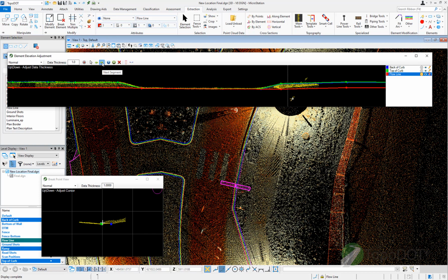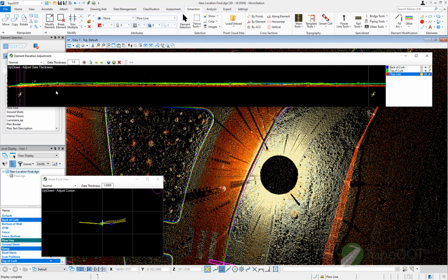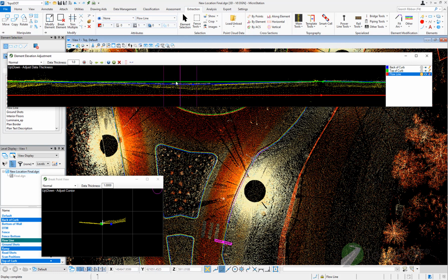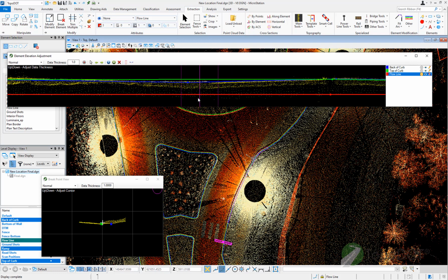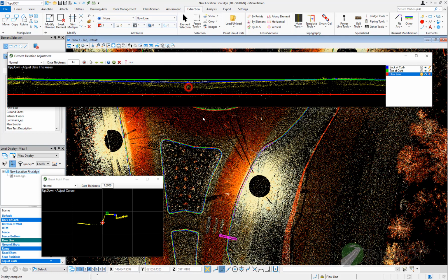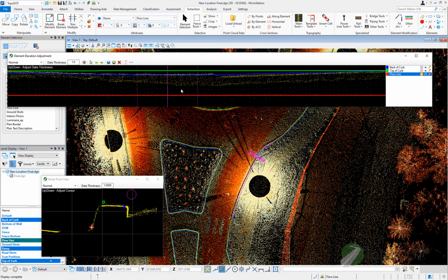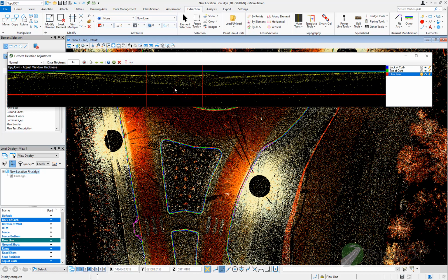So you can quickly address those areas that clearly have issues or that need to be adjusted. And so for example, here we have another area where, because I have the hollow points, that means that those nodes have not been introduced, and I have a flow line there, a back of curve there that is being created properly, but not the other points. So first I'm gonna delete any points I have there, and then I'm going to insert points again right about there.